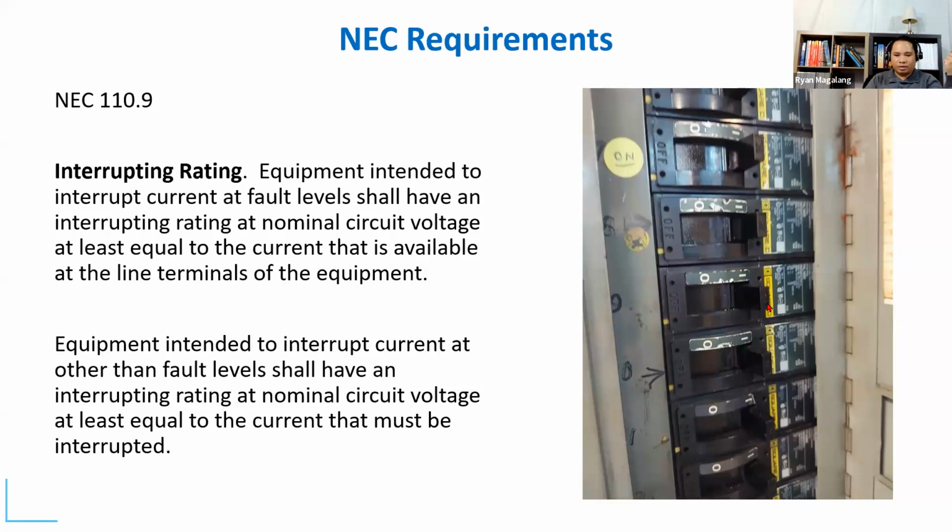So what does the National Electrical Code say about that? In section 110.9, it says that equipment intended to interrupt current at fault level shall have an interrupting rating at nominal circuit voltage at least equal to the current that is available at the line terminals of the equipment.